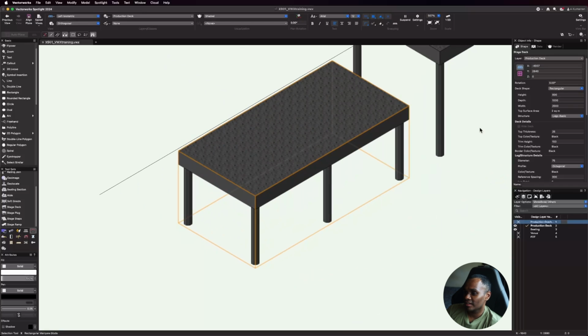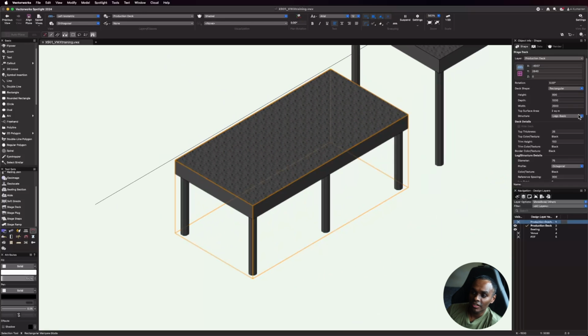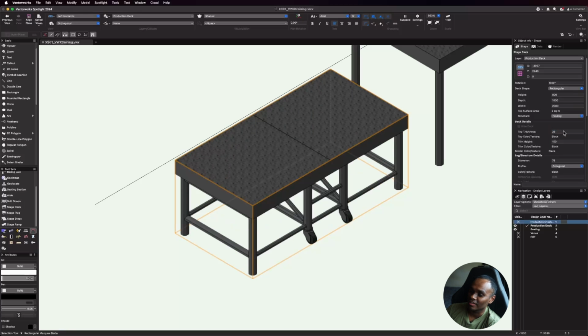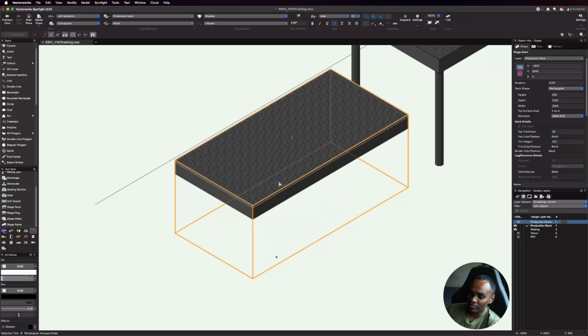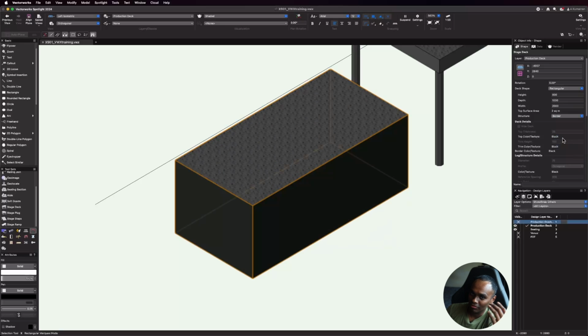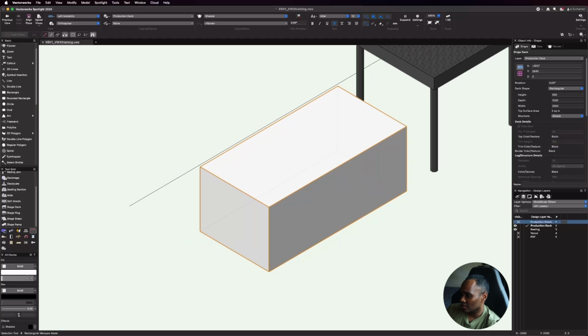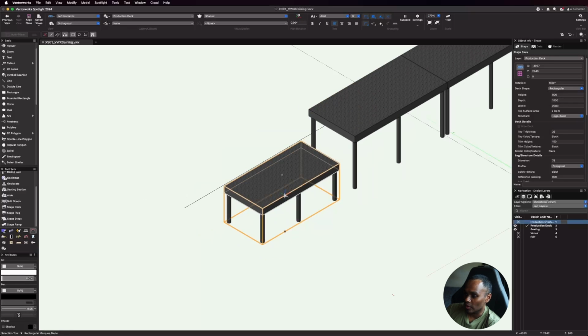You can also see that there is an option here to change the structure. We can use a basic leg structure, or you can have braced legs if you need them to be taller. You can have folding legs, so it looks a little bit like your banquet stage deck. Or just a deck with nothing underneath. Or you also have a border, which is your vinyl skin around the side, or a simplified box just to represent a different height in a space. For us, we are going with the rectangular legs option. So this is what we want.